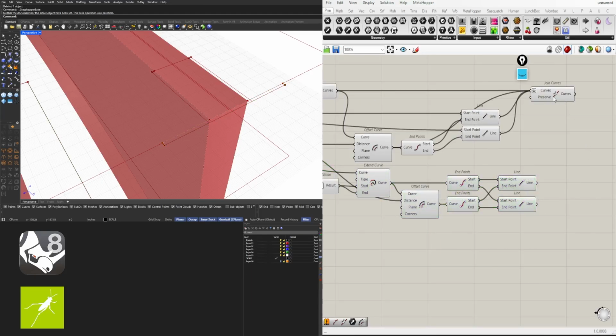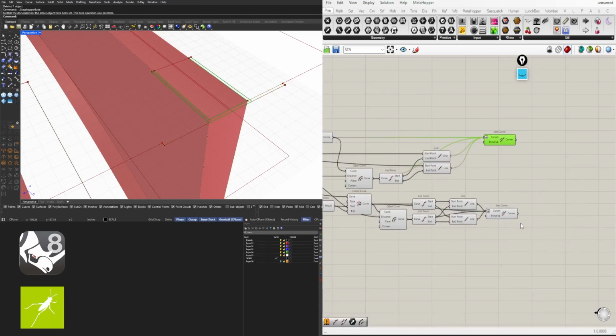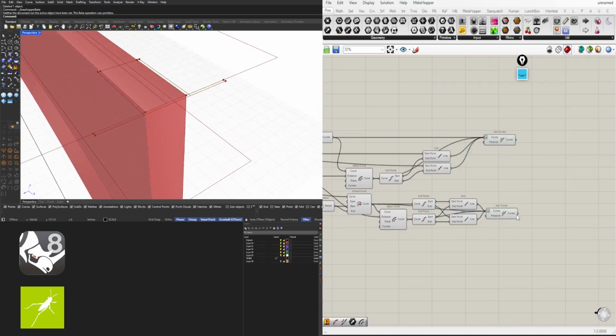So we're creating closed polylines. So I'll copy this and override it with this one, holding down shift, and then this one. Now here we have a closed polyline. So rather than when we extrude it doing Boolean union, which can be inefficient for the script, we're going to use region union between this one and this one. Now notice that it'll join those together, which is what we want.